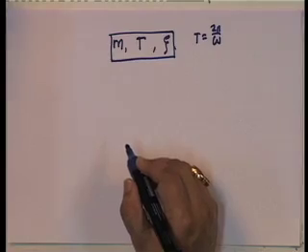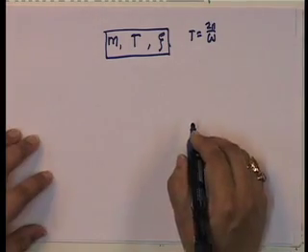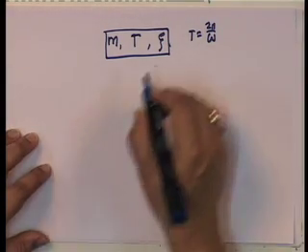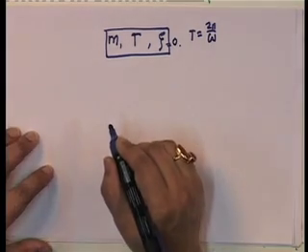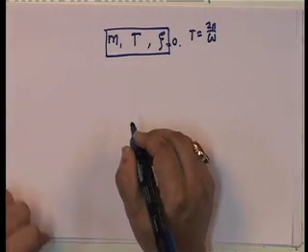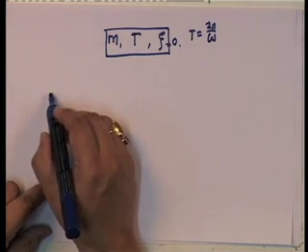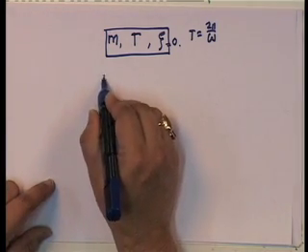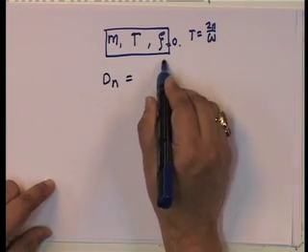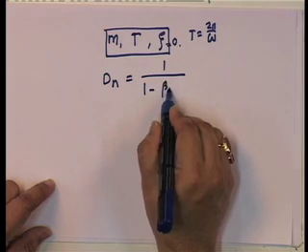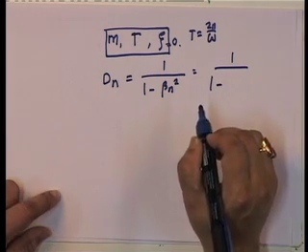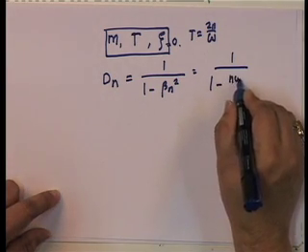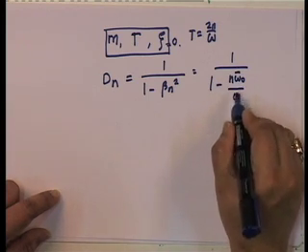Well, the loading is given in this fashion. So, all I need to do is work out how it is going to be, and what I am going to do is take xi equal to 0 for now, an undamped system, and show some numbers. If I look at the solution, then what does Dn become? Dn becomes 1 upon 1 minus beta n squared, which is 1 upon 1 minus n omega bar 0 upon omega, squared.